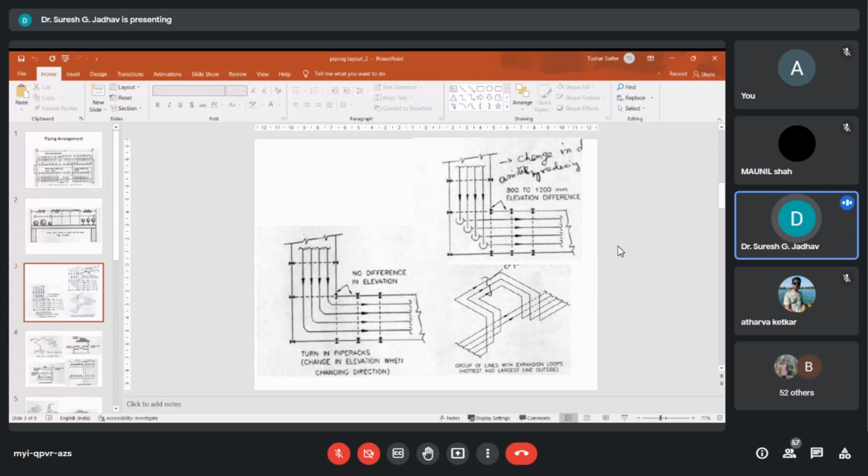The loop shall be arranged with the portion of the loop getting elevated above the rack level by two 90-degree bends. Bends are manufactured by vendor standards, that is MSS SP, so fitting components are manufactured by these standards.